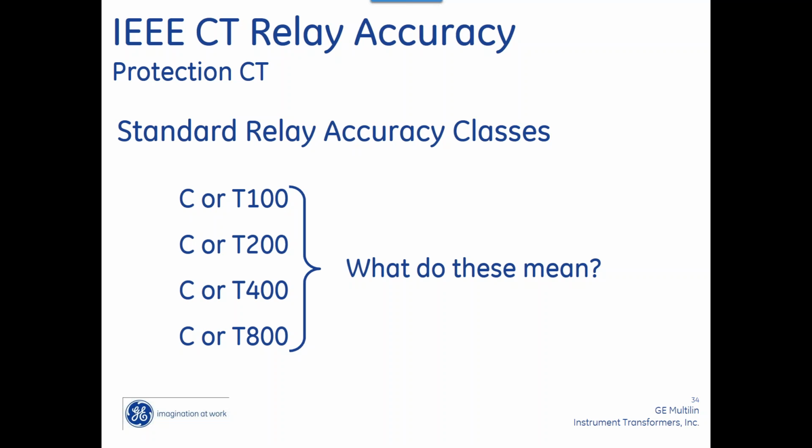Spencer, you're mainly dealing with protection CTs, and we get into a thing called saturation, and from that, I'd rather have a higher ratio, so I eliminate saturation. For metering, if metering's real critical, yes, with a metering CT I could actually lower it if I have a rating factor on it. So yeah, you've got to look at your application. Okay. Any other questions on metering CTs?